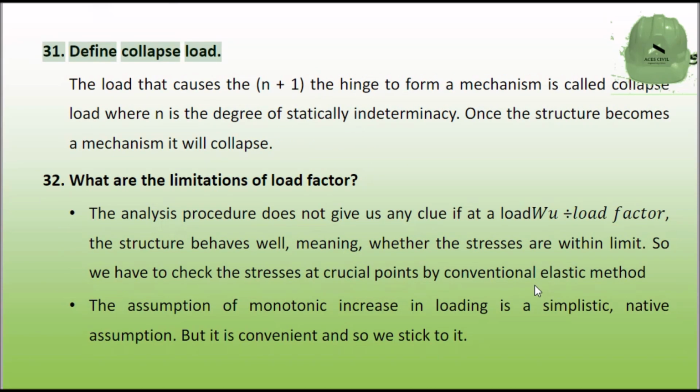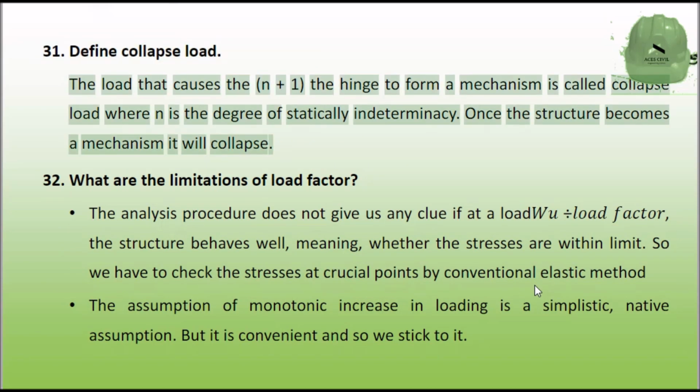Define collapse load. The load that causes the (n+1)th hinge to form a mechanism is called collapse load, where n is the degree of static indeterminacy. Once the structure becomes a mechanism, it will collapse.